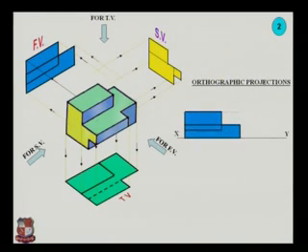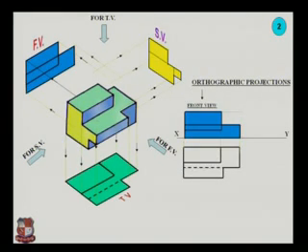Orthographic projection, same. The top view will come above the XY line. From the front view we will draw the projectors of all the corner points of all the lines of the front view, and we will draw the top view by considering the pictorial view of an object. Now we will draw the 45 degree inclined line by taking a point at some angle in the XY line.